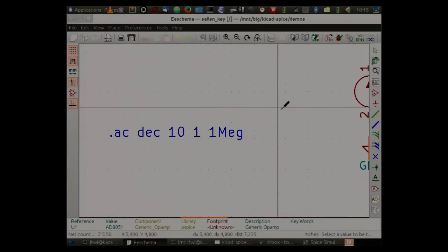At the implementation level, are you generating a spice netlist and feeding that to the simulator core as text, or are you driving the simulator feeding it as sort of direct netlist? So the question is if we are generating a text netlist and passing it to the simulator, or if we are doing it in, let's say, a more binary way. So we just use text.